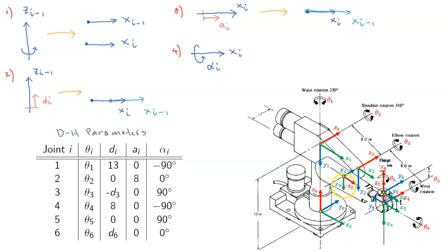Perhaps it's a good time for me to draw for better understanding. First question: we have to rotate this coordinate frame about z2 to make x2 and x3 pointing the same direction. Okay, so let me briefly try to draw here. We are looking at joint number 3, so this is z3, and x3 is pointing downwards. This is x3. So let's rotate first.